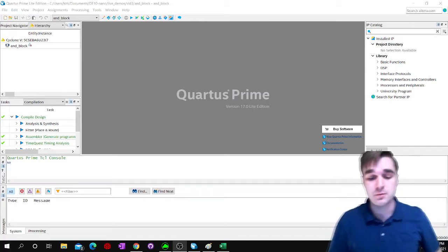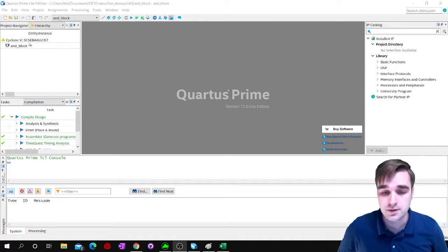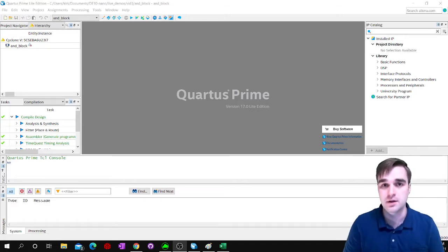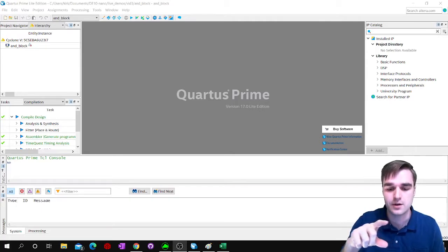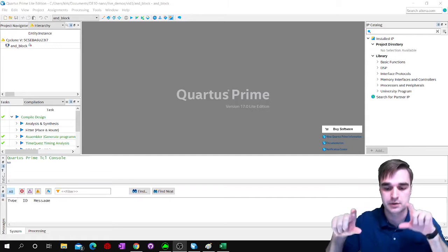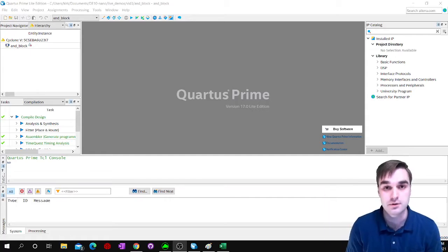But then what we're going to do is derive our equation. That's another thing. The K-map method makes it easier to find what your equation is going to be. Instead of thinking really hard every single time, like, okay, I need to have this logical gate here, and thinking through the logic and building the logic yourself to place your blocks and create a circuit that's going to do what you want.